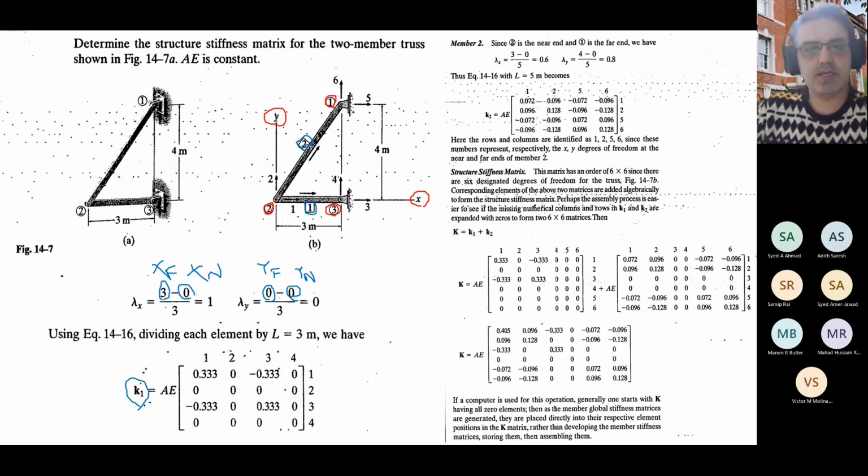Before continuing, I'm just going to emphasize that we need to understand the degrees of freedom as well. For planar truss structures, for each point we have 2 degrees of freedom, which are translational deformation in x and y. But you will see for beam structures or frame structures we have theta, the rotational deformation.